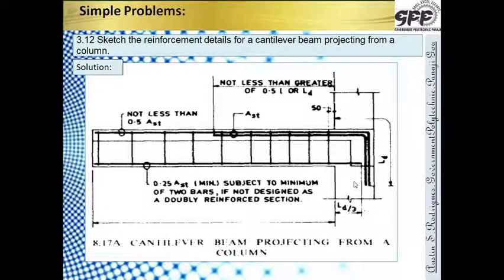Another thing, please note, since this is positive moment reinforcement, it is taken inside the support by LD by 3. So all these things we have to take care of.